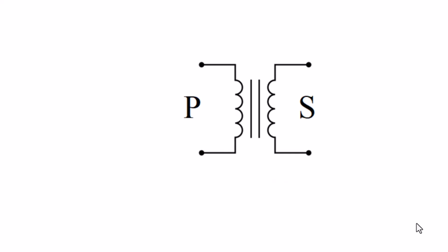You're going to have a thicker diameter, thicker gauge wire on the primary of a step-up transformer because remember, you're stepping up the voltage. If the voltage goes up, then the current has to go down. So in the secondary, you're going to have a higher voltage, lower current, which means in the primary, you have a lower voltage, higher current. So in order to accommodate or handle that higher current, you need thicker gauge wire. So the answer is to accommodate the higher current of the primary.